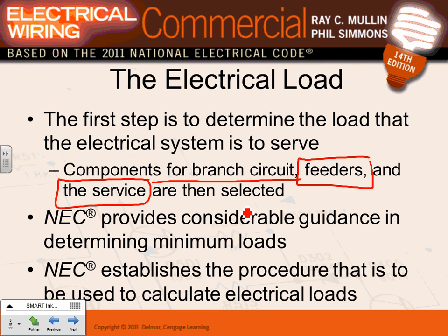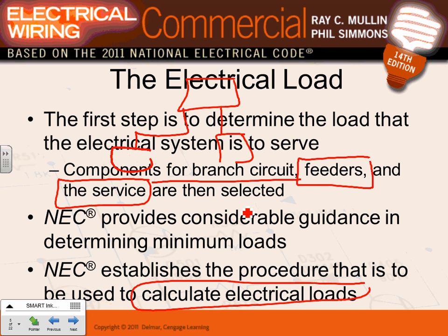So then you have the minimum loads as we did, the procedures to use calculated, the calculation for electrical loads. I'm not going to go through all the step-by-step that we did, all Article 220. But your ultimate solution for the load calculation is, for example, here's my panel, and all the other panels that are tied to this panel, right? That's the ultimate solution. So you need to size the service and all the feeders.